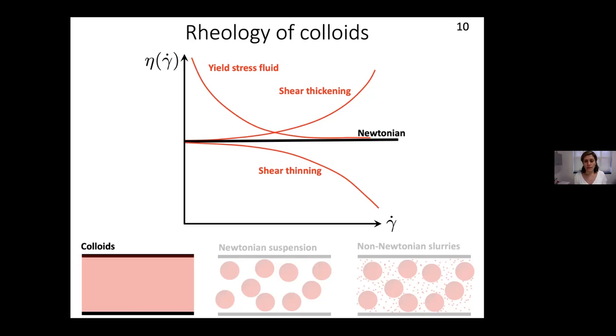That's why when there is an instability in the soil due to human activities or rain or so many other things, we destabilize that, and then we impose a stress that goes above the threshold, and that is yield stress, and then there is a flow. So this is our knowledge from colloidal science, that the fine colloidal particles can interact and give us this rheology.